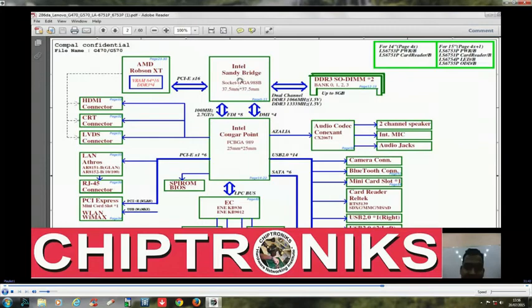Intel has kept the display controller in PCH, but it has kept the graphic processing unit inside CPU, right? So if your notebook motherboard is using an external graphic chip, then the connectors HDMI, CRT and LVDS are connected to the graphic chip, and there are two connections between the CPU and PCH, the FDI and DMI.